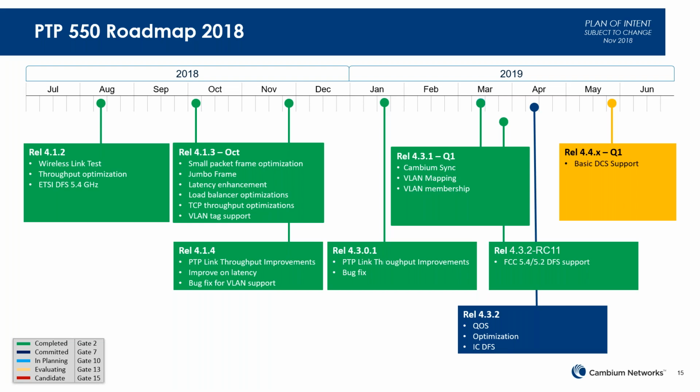If 5.1 has a clean channel that can support 80 megahertz, then we're going to provide 80 megahertz. If the channel is only able to do 40 megahertz, we will do the 40 megahertz. The general criteria is really, no matter what we do, the newest channel should provide better throughput than the existing channel. Otherwise, why would we move, right? So those are the common logic there.